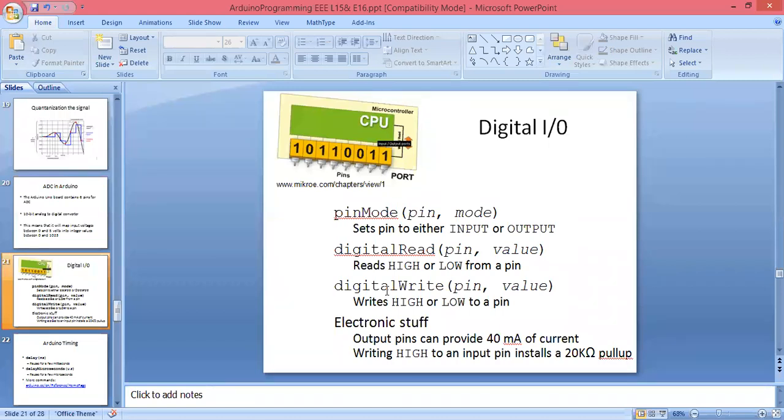So we can use here pin comma value, whatever pin. If you are having D0, D12, D13, we can take that pin number and value. We are giving a high or low value. Here we will write only two values because whenever we are doing programming in Arduino, we use only digital 0 and 1 values. So we can write here high or low. Low will be 0 and high will be 1.